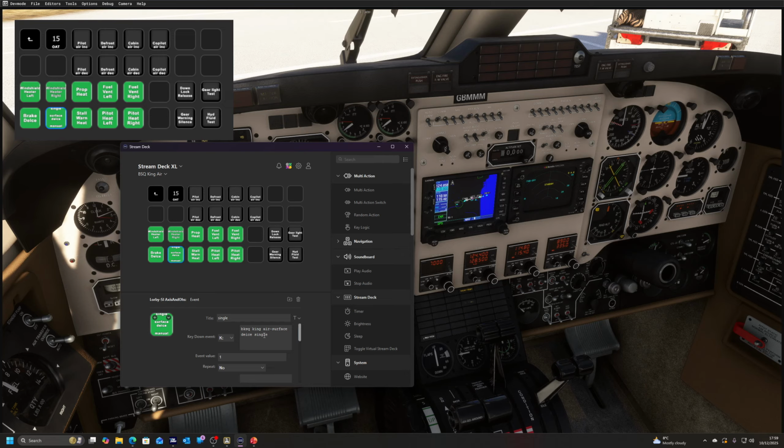It's got two scripts, one for a single and one for the manual de-ice. What the single one does is a cycle for about 10 seconds. The manual one, if I press the manual button, will run for a maximum of 2 minutes. But when I let go of it, then it will turn the de-ice off.